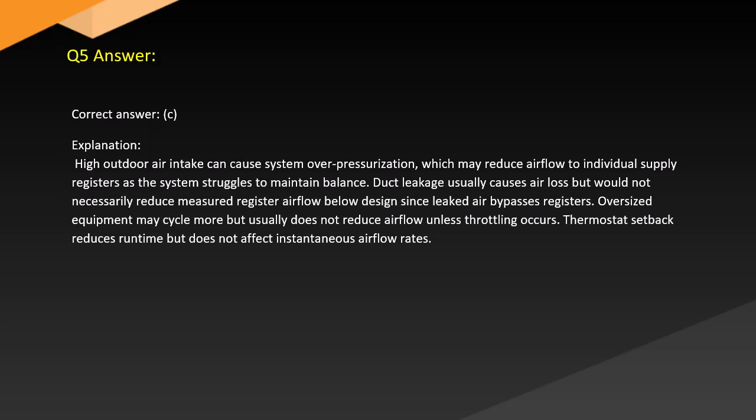Answer. Correct answer: C. Explanation. High outdoor air intake can cause system overpressurization, which may reduce airflow to individual supply registers as the system struggles to maintain balance.